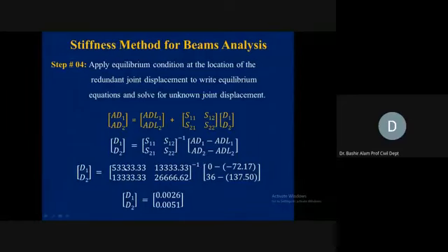We have all these numbers now. The EI value is already embedded in these numbers. So we simply take the inverse of this and multiply with the difference of this matrix. We already found ADL, and you see it is coming with the algebraic sign, whatever it was, this was minus and this was plus. And finally we find D1 and D2 now.